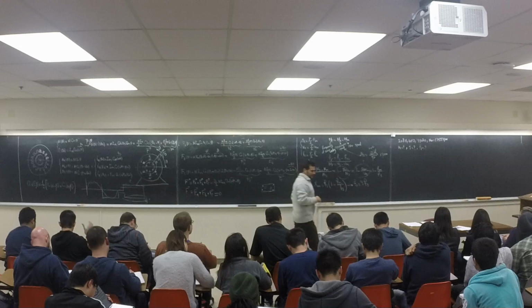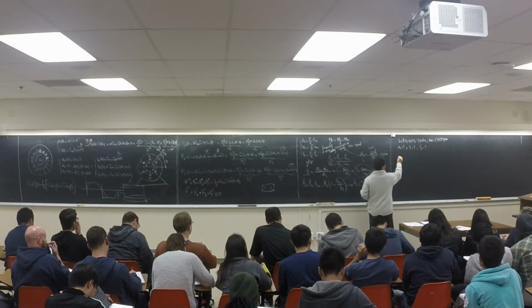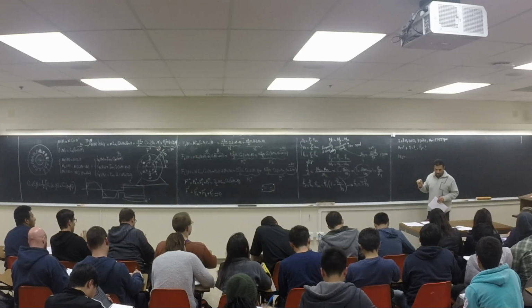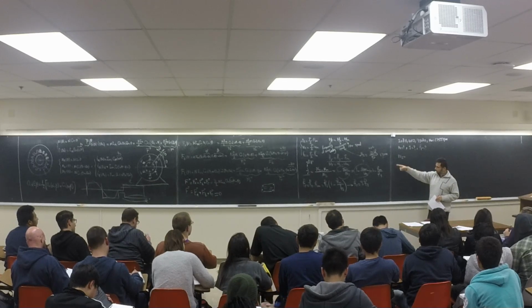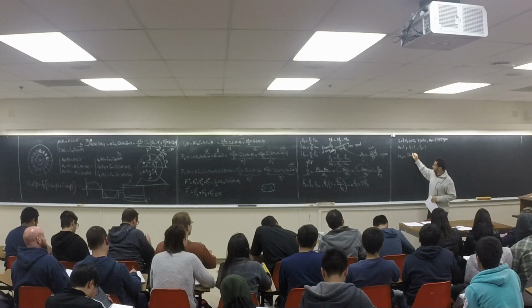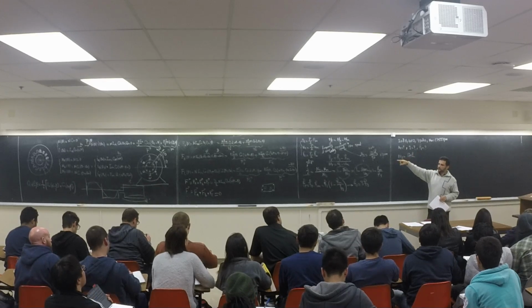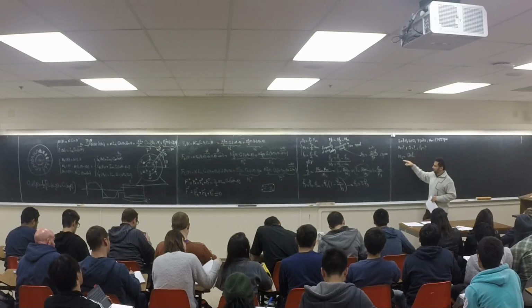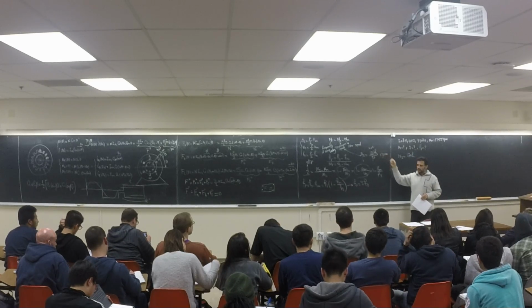So how much is ns? It's 120 f over p. Usually we don't put s anymore. When we say f is the frequency of the supply line, you can put fs also, because this is going to connect to the stator of the machine, right?